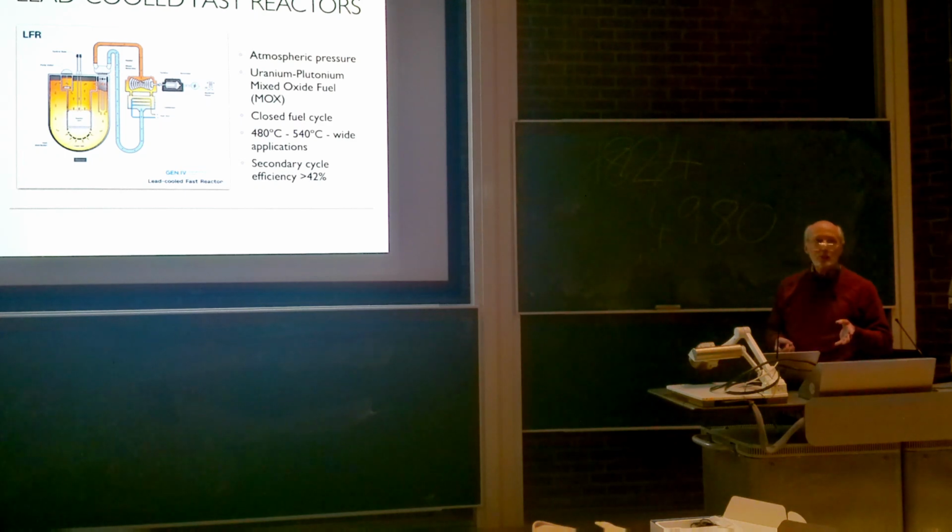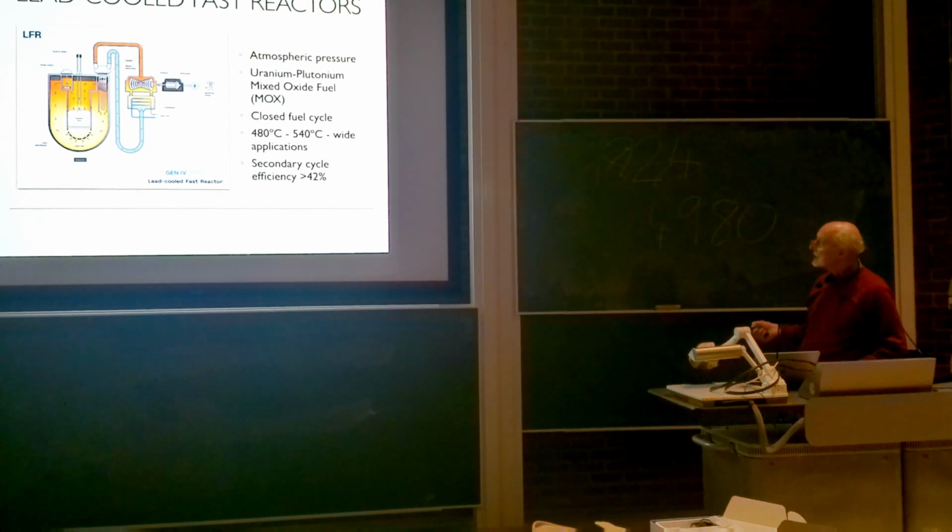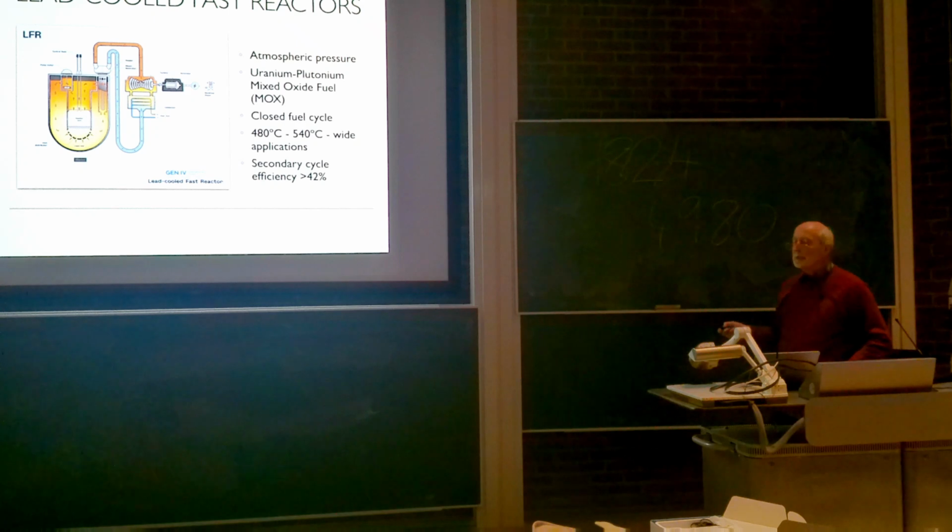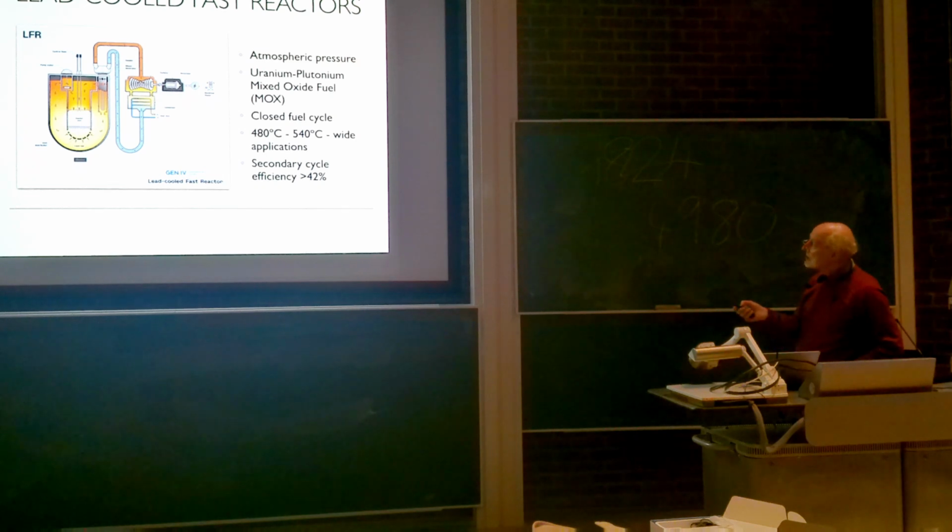That high temperature gas reactor actually was an open system. The spent fuel that comes out is just going to waste. And they claim that this is a very efficient secondary cycle. I think they're normally around 35%-ish as a sort of efficiency of taking the heat from the reactor and converting it into electricity. And interestingly, that runs at atmospheric pressure. So the whole pressure business really becomes a container and containment.